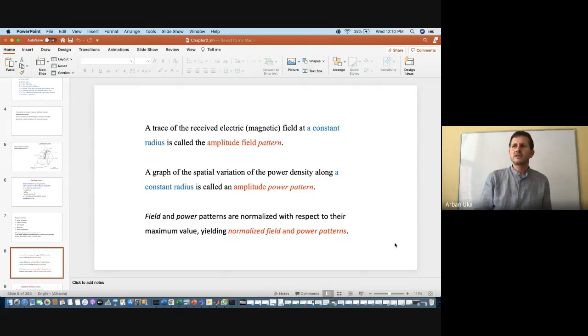1 meter is very close, actually, depending also on the order of the wavelength. But in this case, mathematically speaking, you would have the total power divided by 4 pi r squared, where r is equal to 1. You would have the power density equal to whatever the power is divided by 4 pi. If you are to calculate the power density at a distance of 100 meters, or 10 to the power 2 meters, you would have to divide.